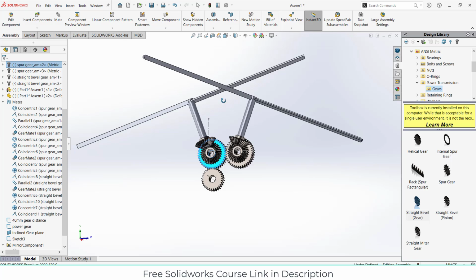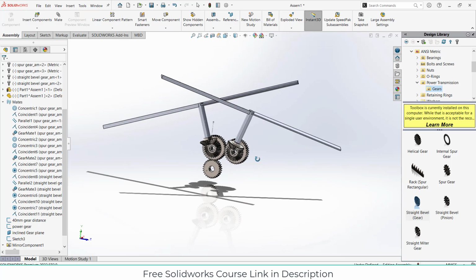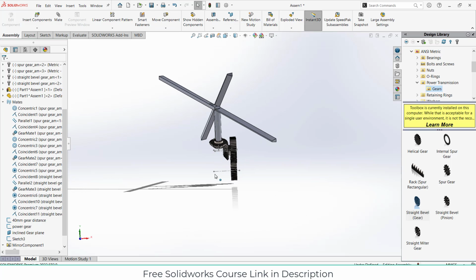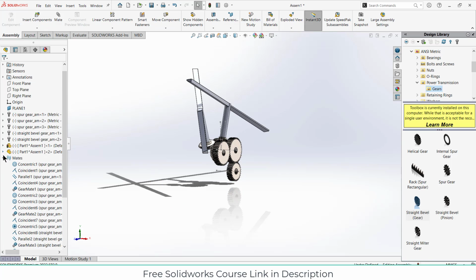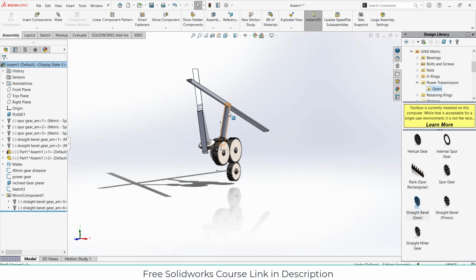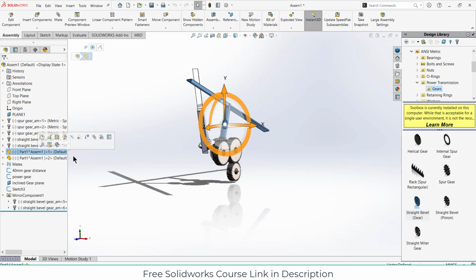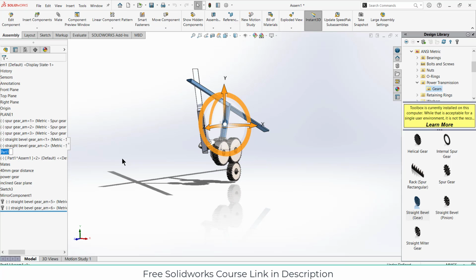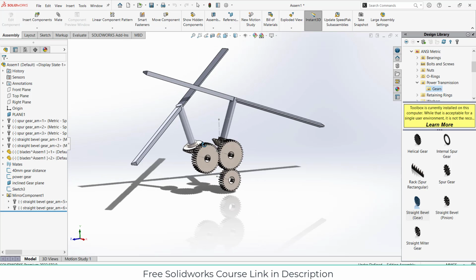Okay, to this point is okay. Now let's make the casing of it. So let's see how to approach the casing. Before I move forward, select this and press F2. As you can see, there is a traffic icon. It is called the rebuild icon. Click on rebuild, select this part, press F2 and let's call it blades. That's okay. After that, we will make the casing of it.